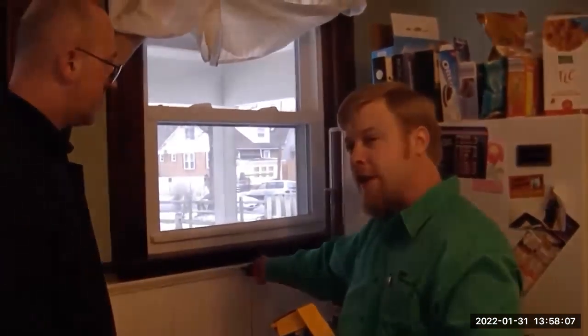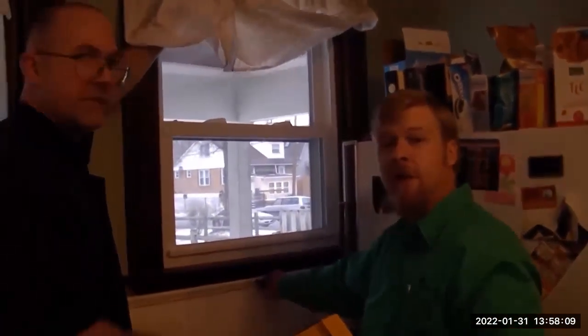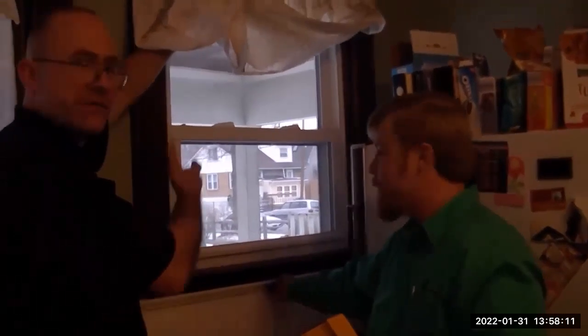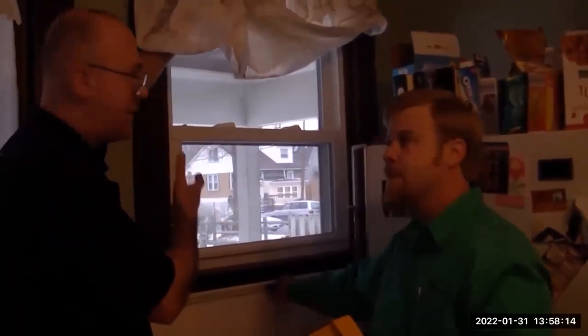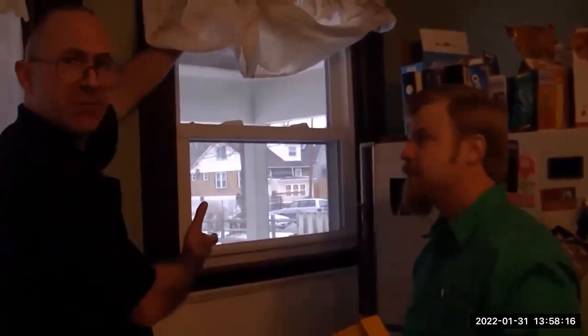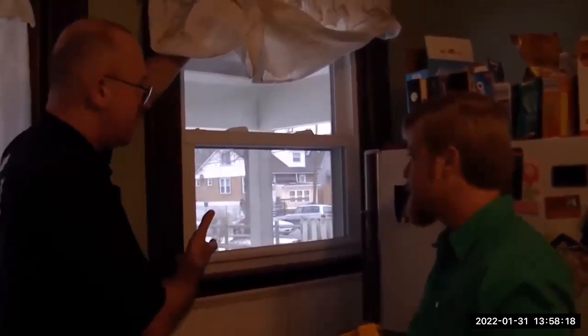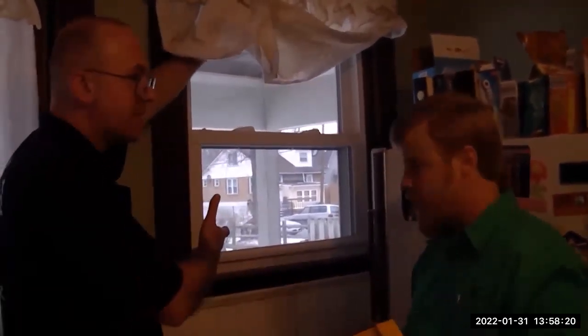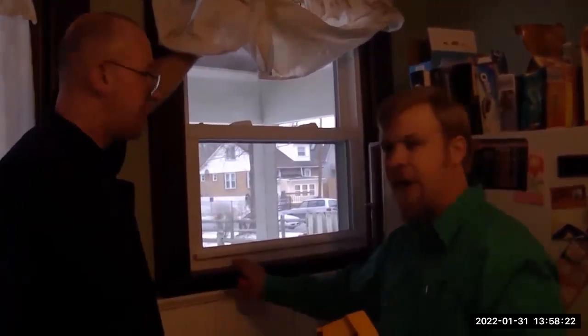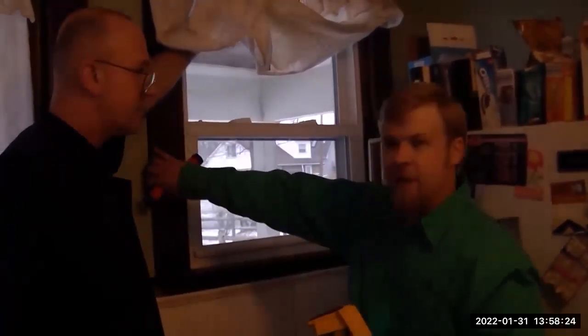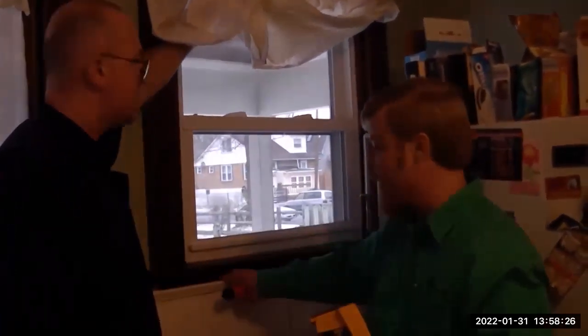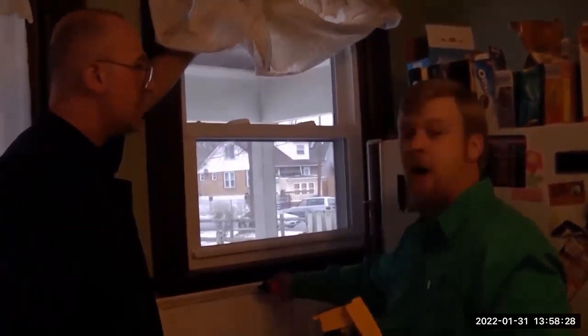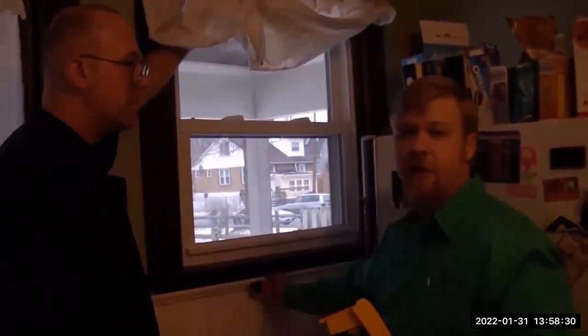So again, all we need to do is just lay a simple bead of caulk, and it'll take care of that air leak. You won't have those full drafts. So this is really an installation issue. All these times people spend so much money on new windows and they're not getting the performance of it simply due to a deficiency in the installation. Correct. A lot of the times when they install brand new windows, they neglect to seal around the window itself and around the trim here, which more often than not is where you're going to get your air infiltration.